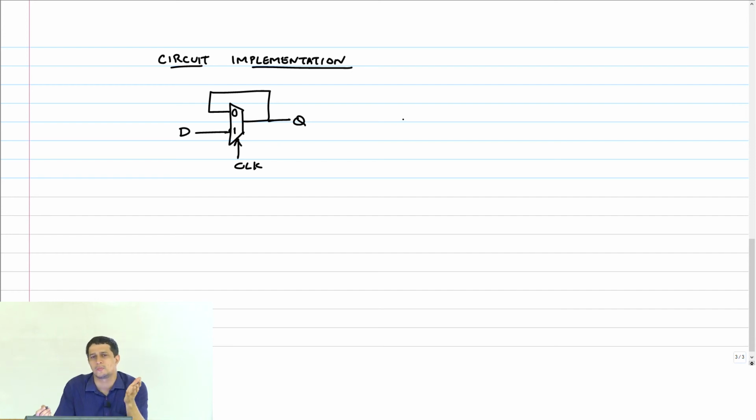The best thing to do for a multiplexer is, what's the best circuit implementation for a multiplexer? Transmission gates, right? A pass transistor is just one NMOS or PMOS. A transmission gate is a combination of them put in parallel, right? So obviously we'll do this.